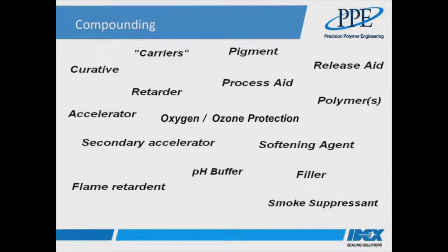Process aids tend to be low molecular weight materials leading to volatile outgassing in vacuum or high vacuum applications. Pigments to add colour are mainly metal complex based. If you see a green O-ring, for example, it's highly likely it will have a chromium oxide based filler system. This can then be released through erosion processes over the lifetime of the seal in a process tool, although clearly this also depends on the process chemistry. The net effect in these examples is that the semiconductor process becomes uncontrolled, or even worse, the substrates can become contaminated, leading to changes in device characteristics.